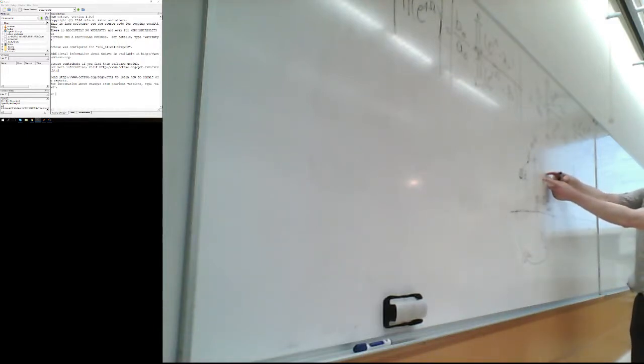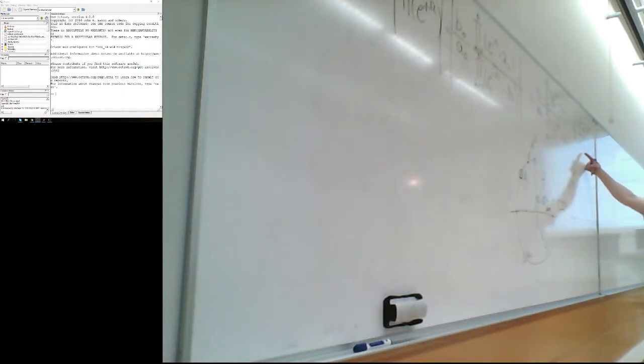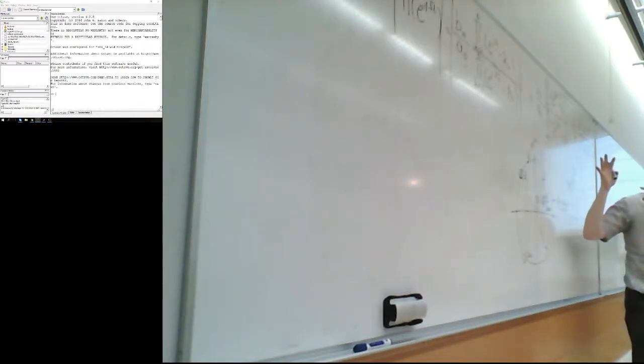Very close to that one. So our denominator is 0.1. So the amplitude goes up over here. Now we can start connecting the dots. So that's how the amplitude response relates to this zero-pole plot.